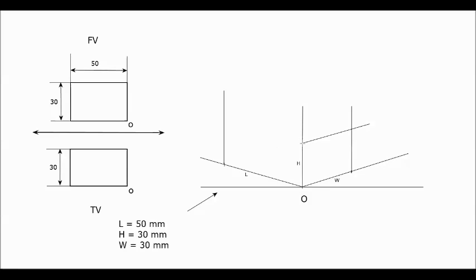Same way, from the height marking, you have to draw a line parallel to the 30-degree inclined line on the left side of the height marking. Because of these 30-degree inclined lines and the vertical line through the height and width marking, you will get two new intersection points.